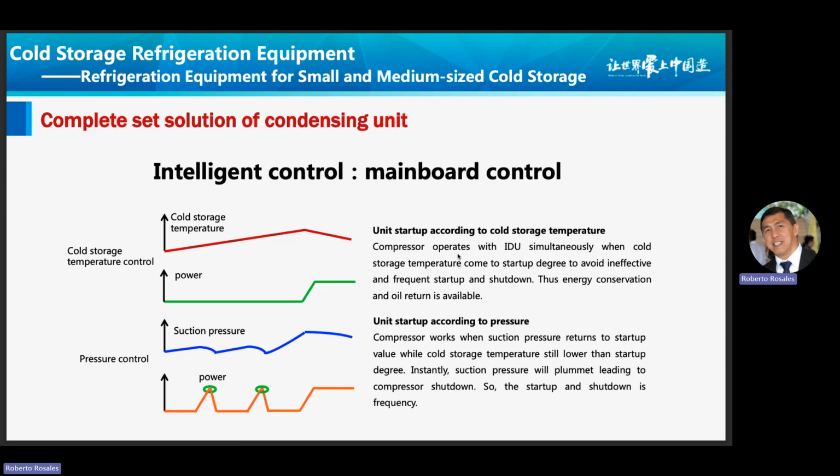Unit startup according to pressure. Compressor works when suction pressure returns to startup value, while cold storage temperature is still lower than startup degree. Instantly, suction pressure will plummet, leading to compressor shutdown. So the startup and shutdown is in frequency.